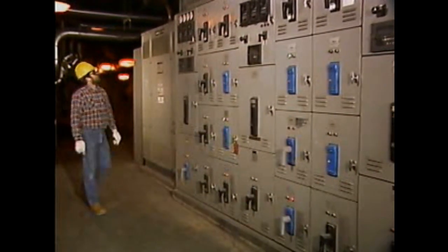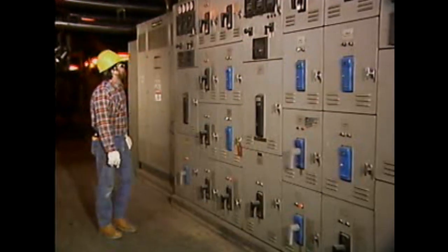The procedure that we just saw dealt with the protective function of a circuit breaker, interrupting current flow to protect a load, such as a motor. Another procedure, known as racking out a breaker, can be used to physically lock out a load from its source of power so that de-energized equipment can be worked on safely. Racking out a breaker involves physically disconnecting the breaker from its electrical connections. Let's watch this operator go through a procedure for racking out a breaker.